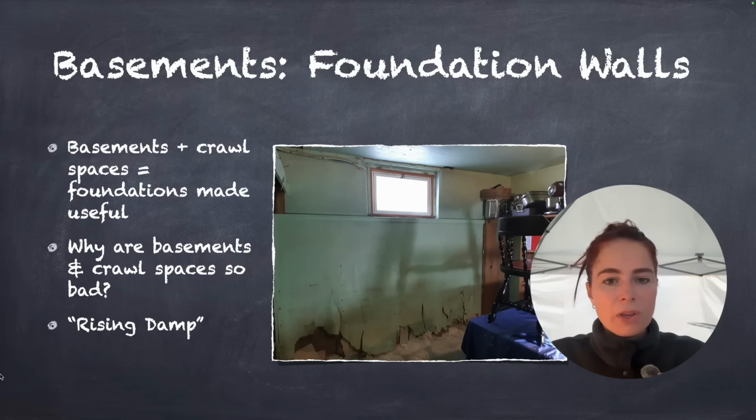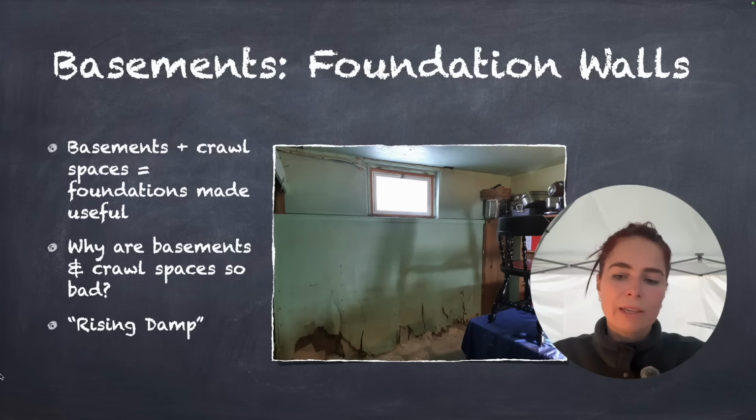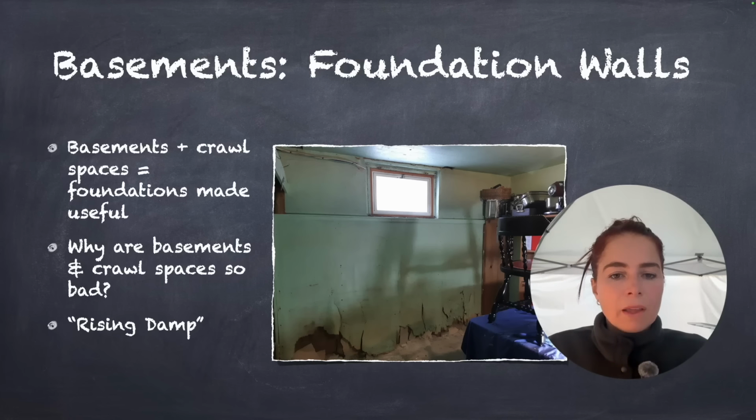So that moisture is always trying to get in, and a lot of the time it does, despite our best efforts to stop it. You add to that modern construction like drywall, carpeting, wood framing, and you end up with mold, because those are materials that love moisture. They hold on to it and they do go moldy.